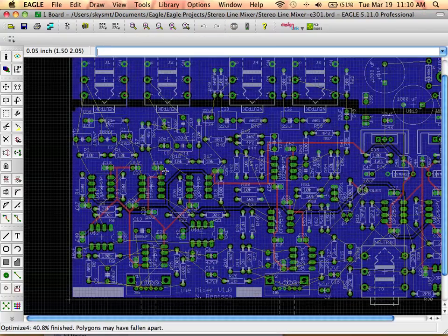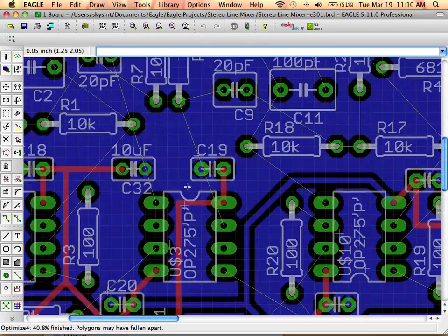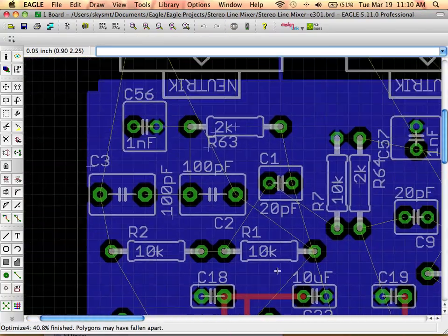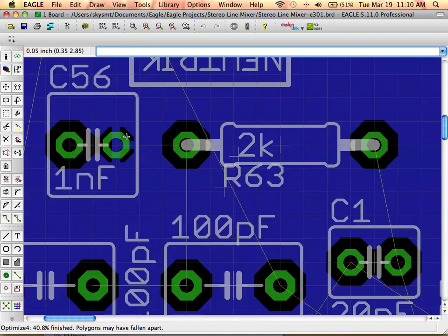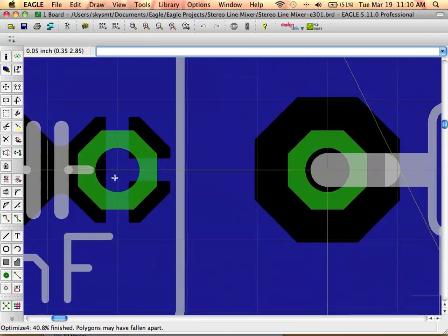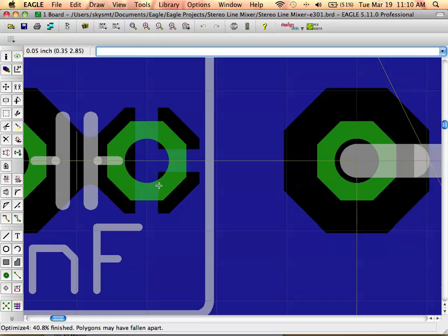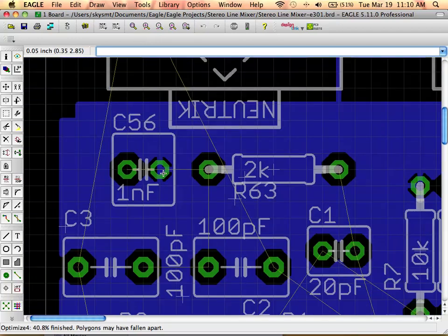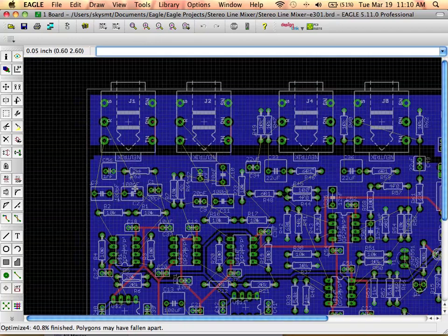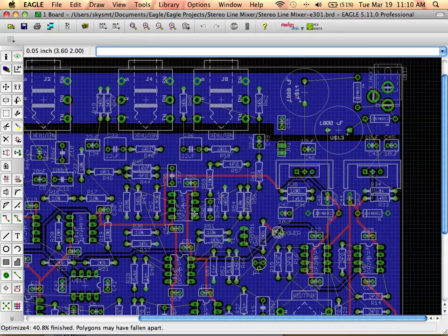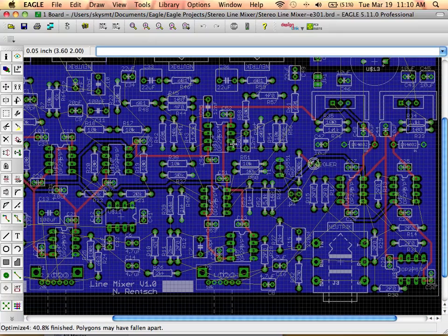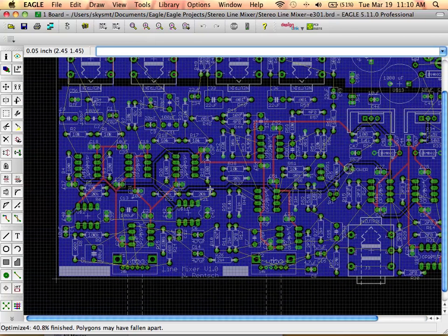Okay, so I do that, and there, bang, everything is basically grounded where it should be. And remember, that's just done with these thermals connected to the vias or to any holes. So that's all you're basically going to see. There are no ground traces because everything is just run in the pour. Okay, and then I can auto route physical earth.